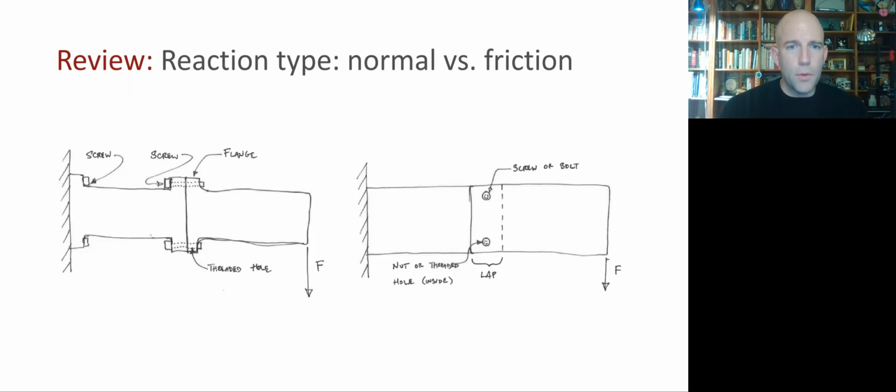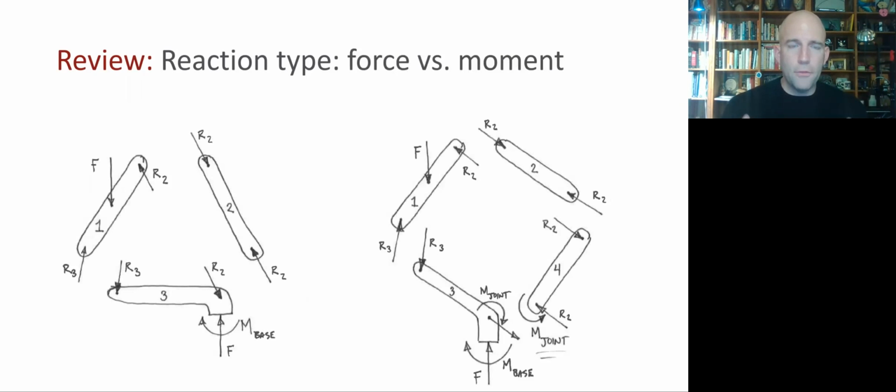Another thing that we might want to think about is whether we have reaction forces or moments at our joints. As we just saw a moment ago, when we have that beam that has a bending moment in the middle and we load it, we need these two opposing forces at the joint in order to create this couple, this force couple that creates a moment opposing the applied moment. It's much simpler if we can just react out one force at a joint.